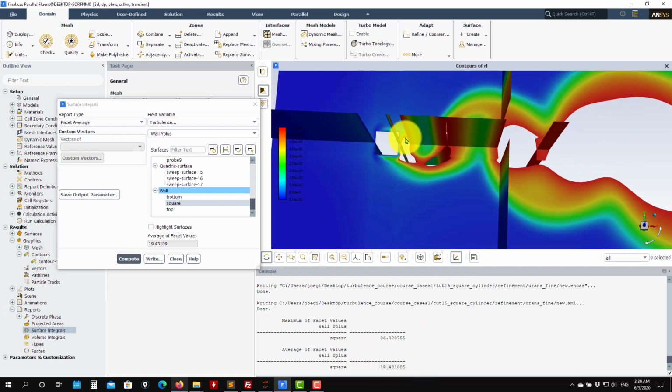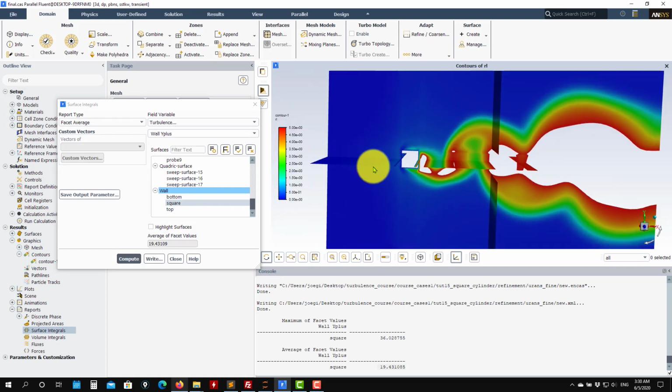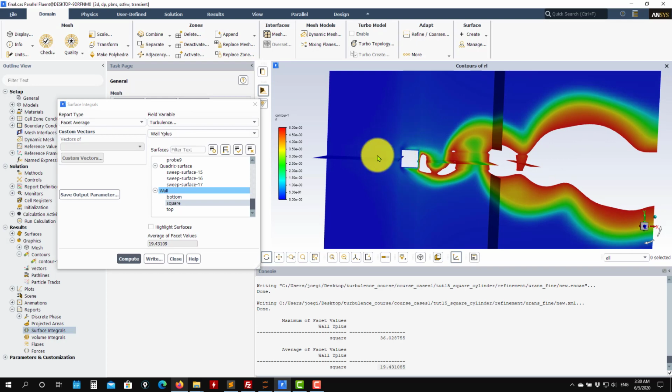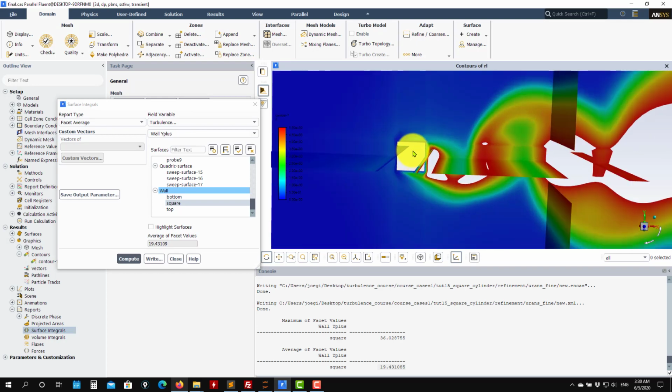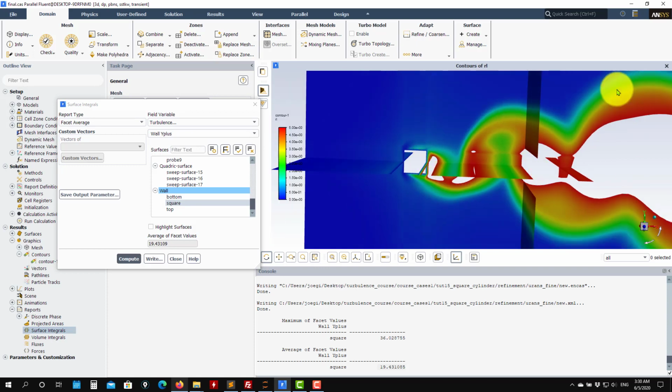Remember it's better to do it at the mesh level, using the meshing utility, but as you want to do it here, it is possible. So let's add two refinement conditions, one for y plus, close to the wall, and the other here in the wake.